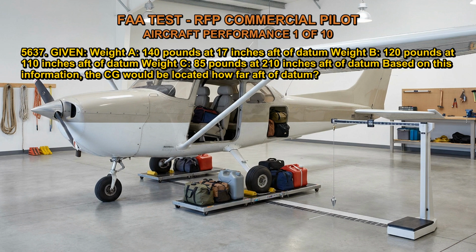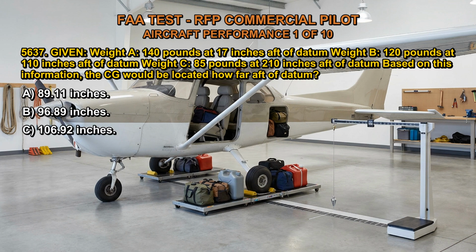5637. Given weight A, 140 pounds at 17 inches aft of datum; weight B, 120 pounds at 110 inches aft of datum; weight C, 85 pounds at 210 inches aft of datum. Based on this information, the CG would be located how far aft of datum? A. 89.11 inches. B. 96.89 inches. C. 106.92 inches.